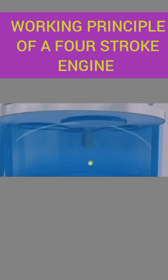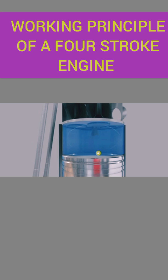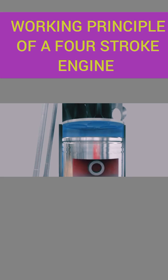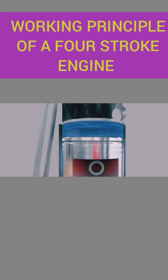So now, during the compression process, there is an increase in temperature and pressure, making it very high. That produces heat, our second element of combustion. So now you see we have oxygen. The oxygen has been compressed and it gives us heat. So now the next component that we'll be looking at will be the fuel, which will be at the next stage. Now we are on the second stage, which is called the compression stroke. So this stroke is what helps produce the heat of compression, from the name compression ignition engine.